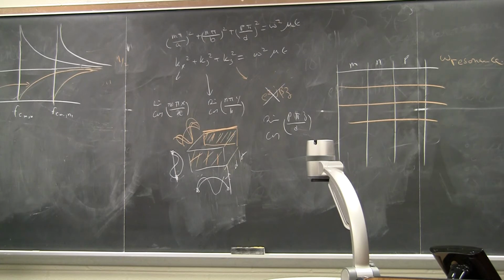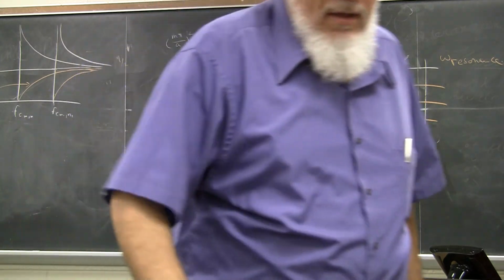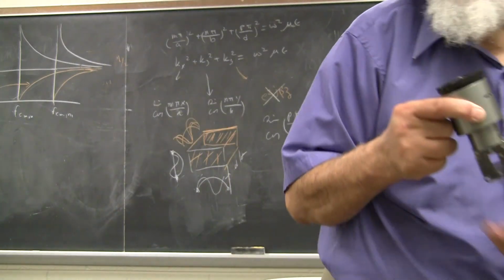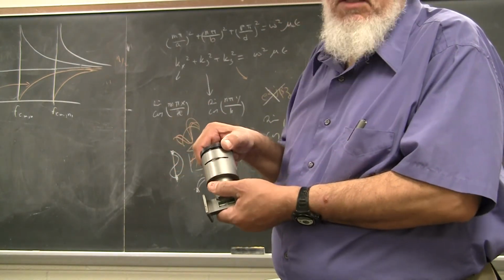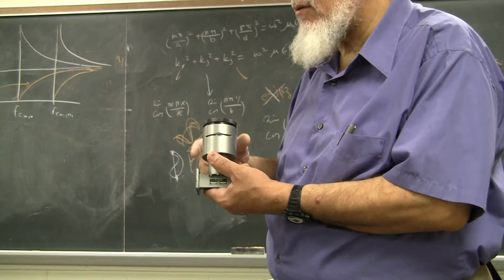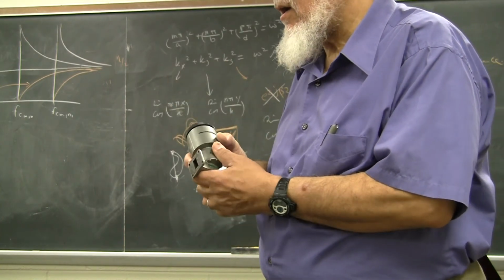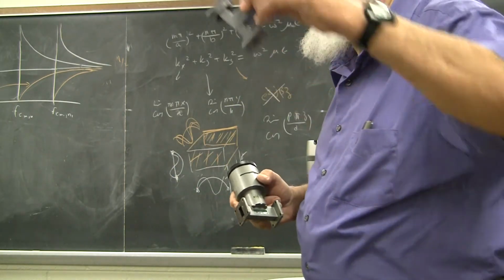Okay. Here's the rectangular, and this one here for the circle. These are the resonant cavities. So what you have here is a cylindrical resonant cavity, because obviously of the ease of machining, right? You can make a piston in a cylinder much easier than making a square piston in a rectangle. Here's a square piston in a rectangle.